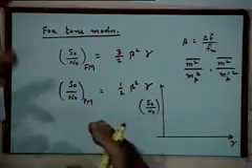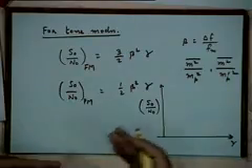In general, we have discussed under what situations FM or PM will be superior, but specifically for tone modulation, FM is superior by a factor of 3. That means it produces 3 times the output SNR produced by PM for the same value of gamma. 3 times means 4 dB, so it is superior by 4 decibels.